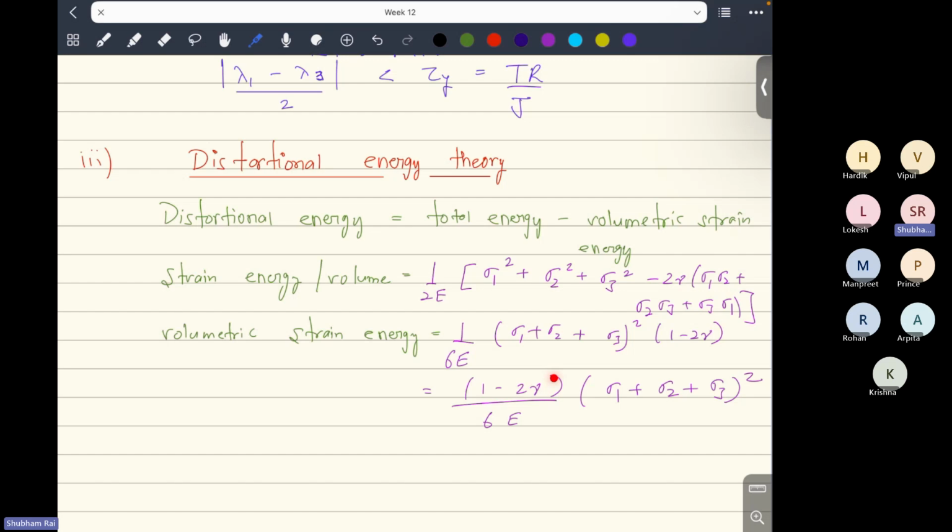If you stretch those honeycomb-shaped unit cells in one direction, transverse to that direction they will get extended, not compressed. So two kinds of materials have negative Poisson ratio. There are many materials, but I have given two examples: one is human muscle, and the second one is auxetic materials. And they have a lot of applications